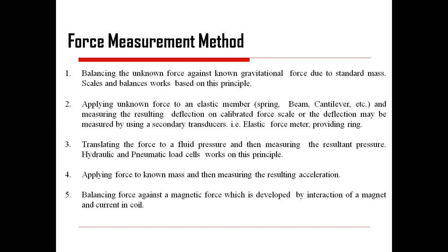There also, if you apply some weight on that deadweight tester, you are exerting some force on it, and the reverse force you apply to the liquid will try to generate the output. As soon as the weight gets lifted, you consider that particular pressure, and that pressure is calibrated in terms of your required output. That is the part of pressure, but you can consider the example for force measurement in this aspect also.